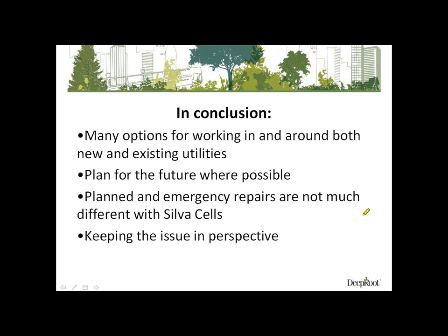The question, as far as filling with stone, yeah, and we have some pictures of projects where they've done stone, and they've done sand, and then we have some where they've actually layered them. So you maybe have stone in the bottom with a layer of filter sand over the top of that, and then the upper half of the Silva Cells is then filled with planting soil. So you have almost like you would a rain garden design, a 3-layer where you have a drainable soil mix for the trees, and then below that you have your filter mediums. So yeah, there's a number of different things.